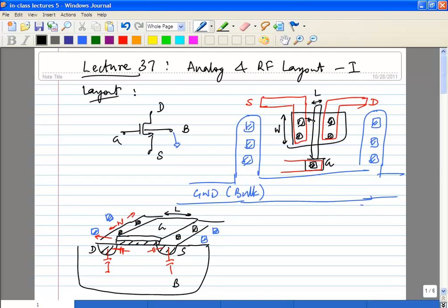There have been cases where, for example, capacitances on top of the transistor to the gate, people have got burnt. They didn't set the switch properly, and then you get a completely crazy result. You do your LPE simulation and it looks fine, but you get back your chip and your gain is maybe 6 dB lower, half the gain. Things like that have happened, so be very careful about this.